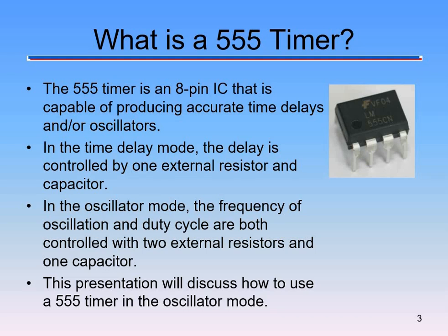We're going to go through a data sheet that goes through what all the different tagging is on that. Notice the circle on it though. That's your reference point so that you know which way it has to be put in. Remember, if we didn't put the 555 timer in right in our dice calculator, things weren't going to roll right, like if we accidentally put ground where power is. But it's what we use to create time delays or oscillations.